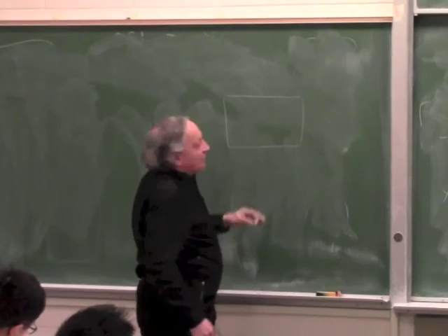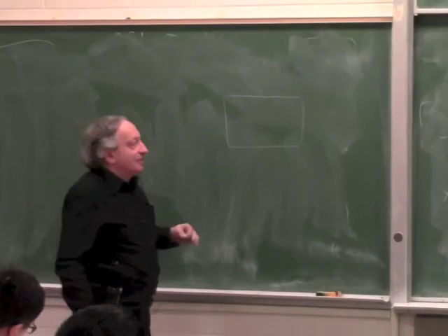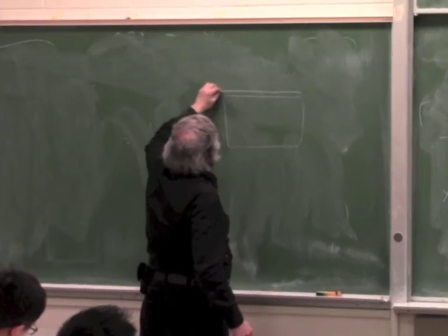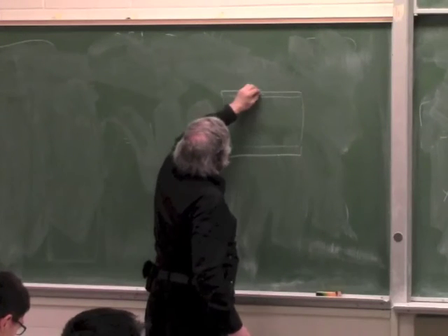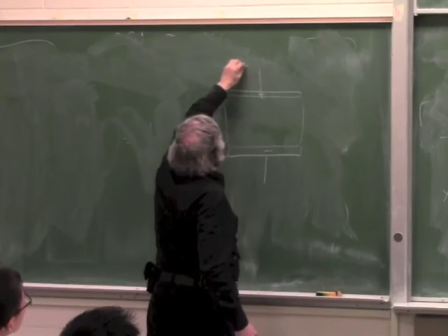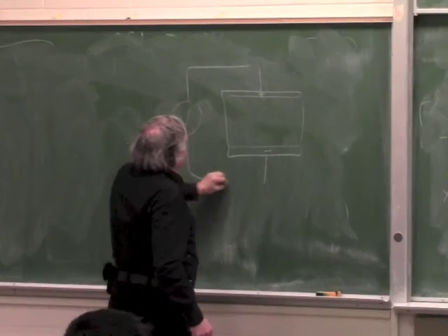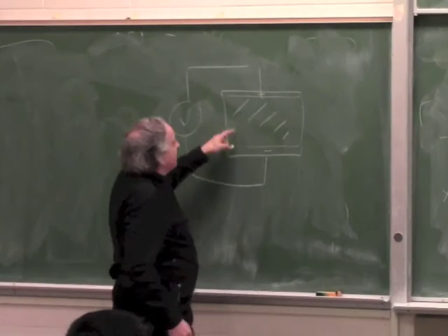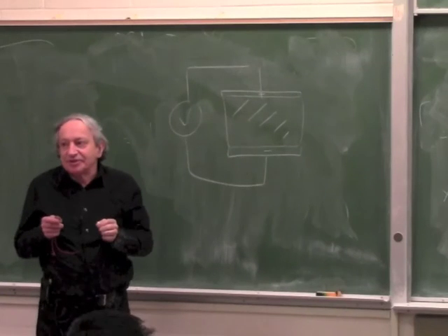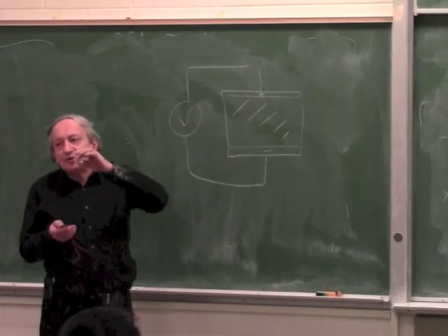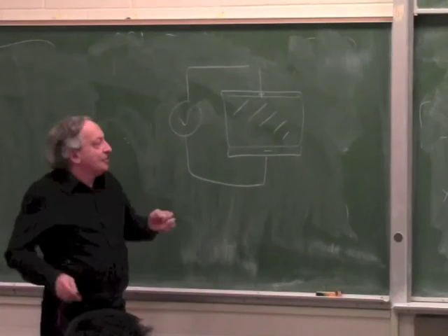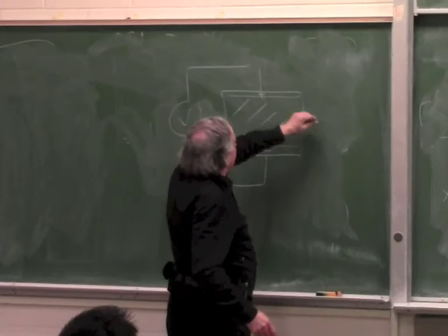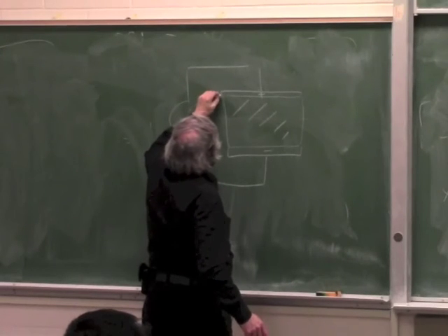you take a piece of crystal, typically it's crystal material, you put 2 electrodes on it, let's say plus and minus, and when you put a voltage on it, it's voltage driven, not current driven. When you put a voltage on it, that crystal changes dimension. And depending on how you orient the crystal, you can make it change dimensions this way or make it change dimensions this way.